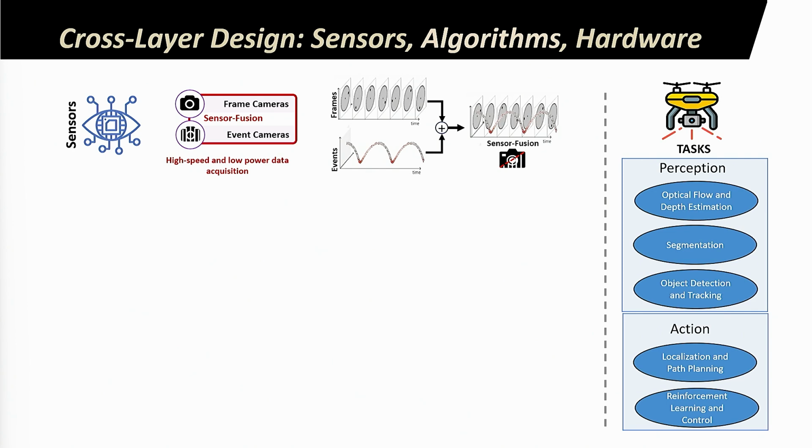The difference between the two cameras is that in the standard frame-based cameras, which we're all familiar with, frames are available, but in a DVS camera, which is more neuromorphic, if I may say so, when there's a relative motion between the camera and the object, spikes are produced. And those spikes are going to be quite important, and the timing between the spikes is also going to play a role in determining what kind of optical flow I have. So sequential information turns out to be quite important.